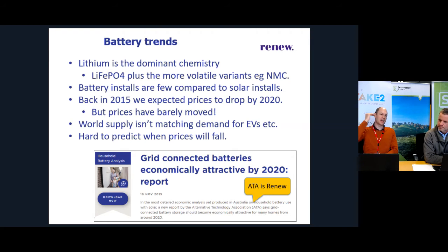So that gives you an incentive. If you can reduce that peak at that specific time, then that's going to have a pretty significant impact on your bill. And yes, batteries can do that. The challenge is how do you deploy that battery capacity? Because if you see that you're in a peak, do you blow all your battery capacity on that peak? And oh yes, we've done really well, we've reduced that peak, but then maybe the next day or even the next hour, you get another peak, and now you've got no battery capacity left to use to reduce it. So yes, it's possible, but you really have to get into specific situations on that.